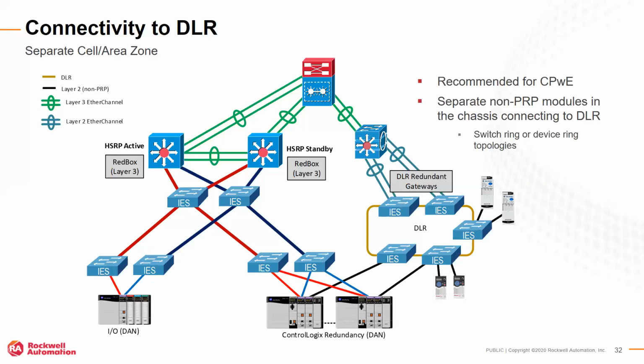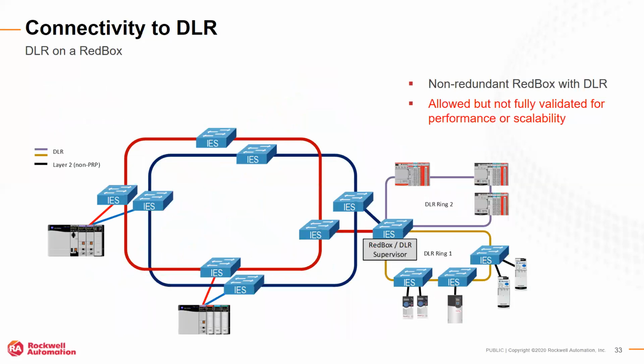That's one way of having two completely separate networks on your ControlLogix redundancy system, and this is how you do it. Actually, there are 3 networks there because they're also using EtherChannel off the DLR network to their access switch. They're using port aggregation as that connection, which is a little different than the DLR and the PRP. There you go. Yeah, thanks, Mike.